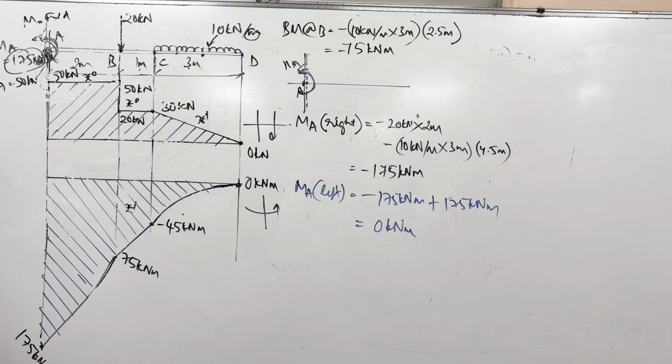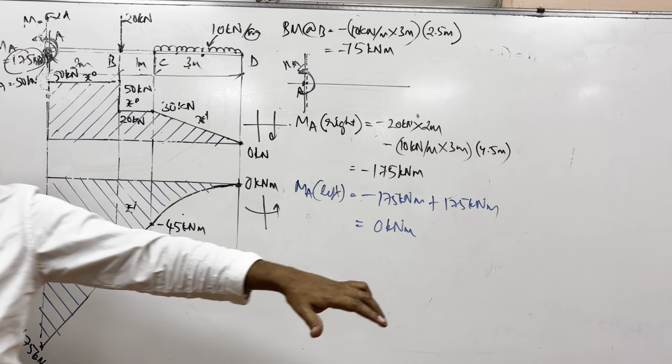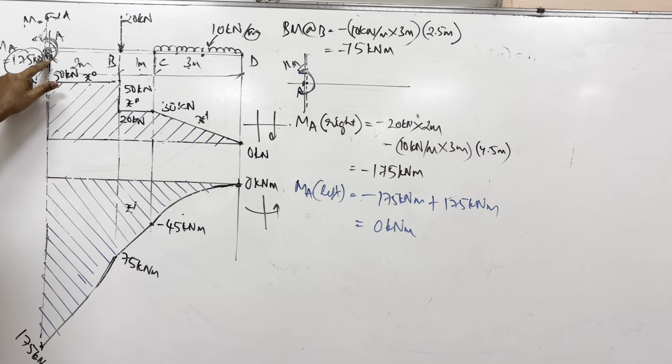Now we can understand why that aeroplane wing had to be made so thick at this point, because there are a lot of loads here. We will have a huge amount of shear load and a huge amount of bending moment. If the wing fails, it will fail at the point where it is connected to the fuselage.